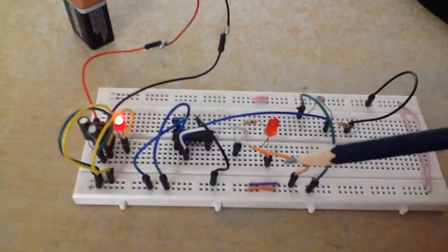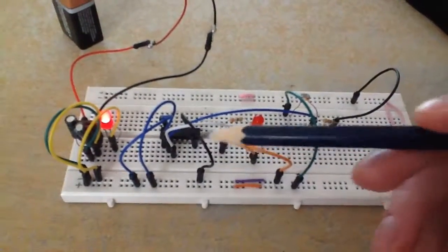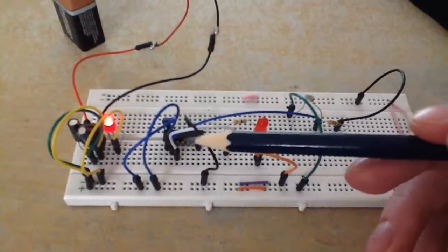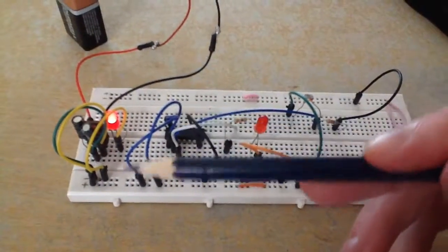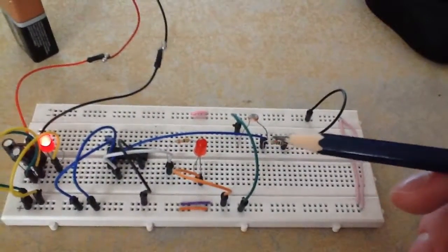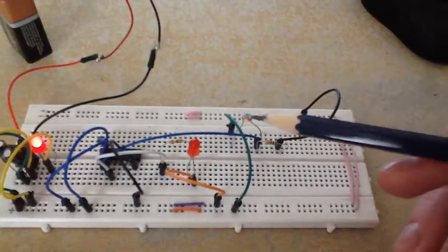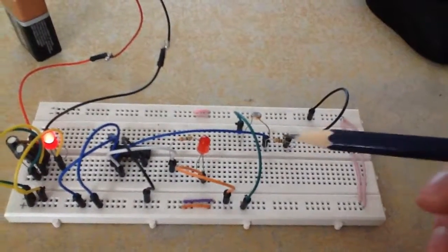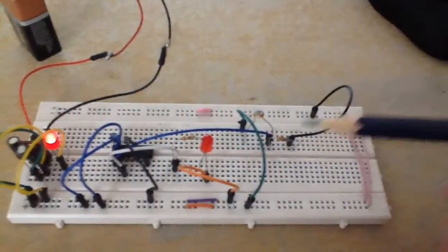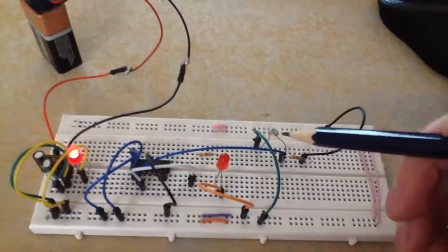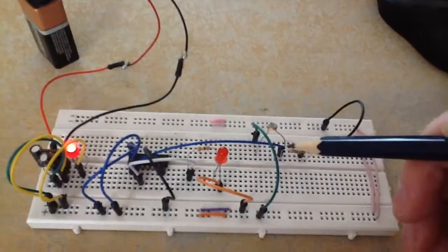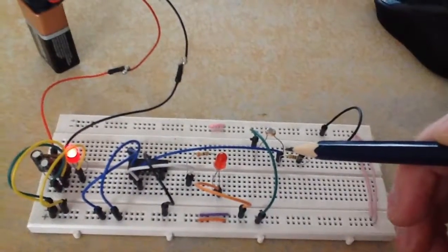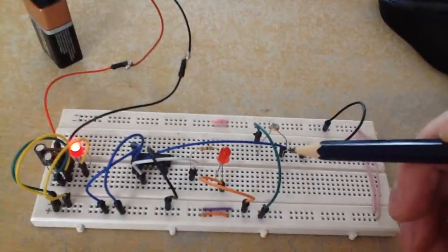In this circuit, we're looking at some applications that we can use the quad 2 input NAND gate in. Pin 1 is connected to 5 volts, which is therefore high. Pin 2 is connected across this voltage divider circuit, where we have a light dependent resistor in series with an ordinary resistor. When I put my finger over the light dependent resistor, the voltage will drop, because the resistance is increasing.